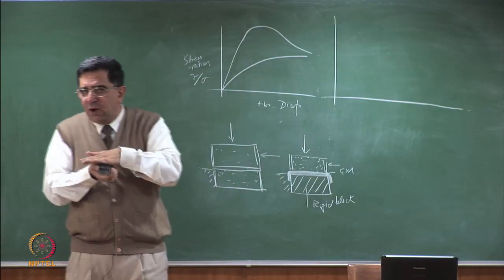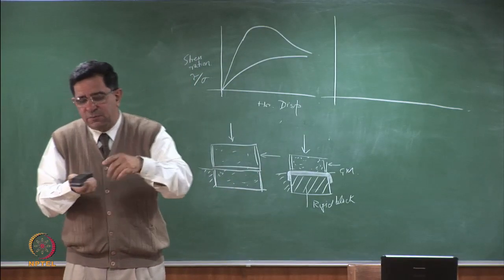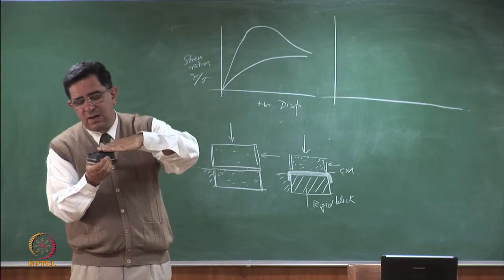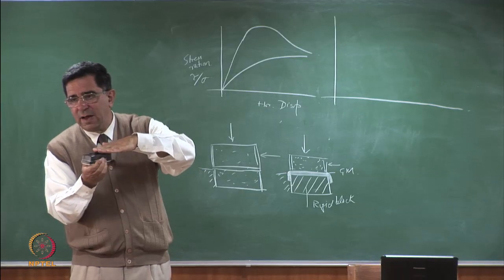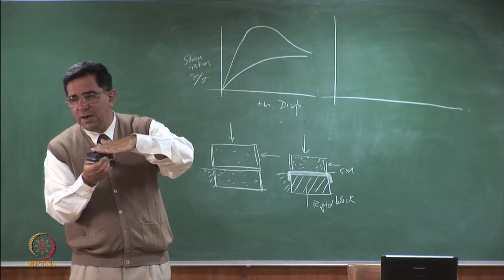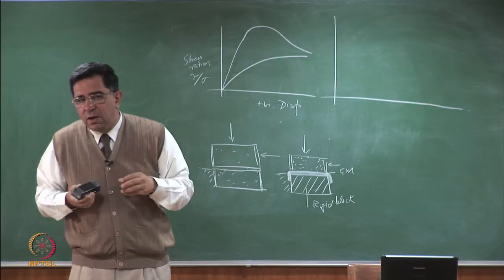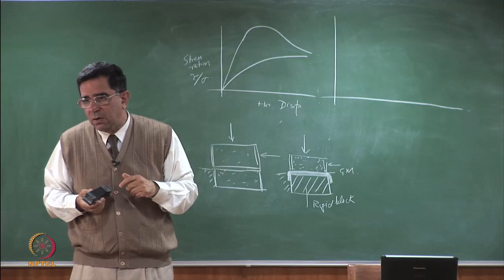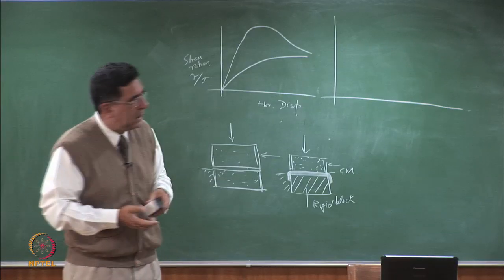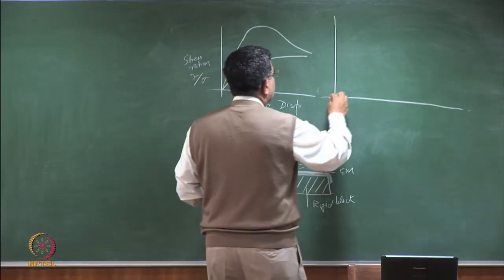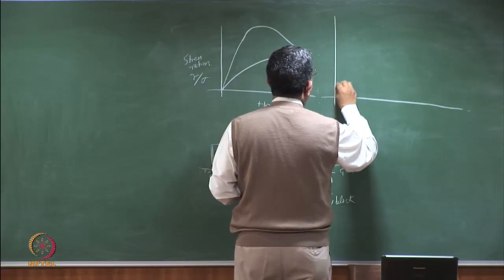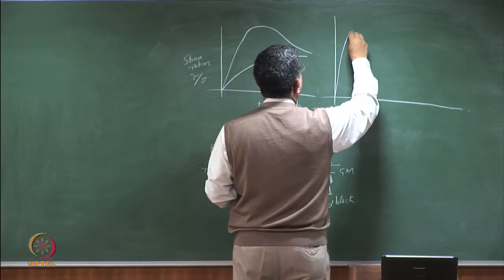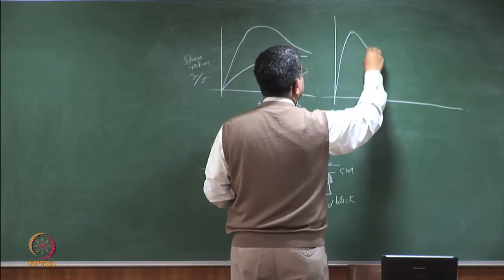An interface shear phenomenon is a slippage phenomenon. This is the bottom, this is a geomembrane, a smooth geomembrane. My soil is here. I move it, I'll get a friction angle or an adhesion. So will it require 10% strain to get a peak, or a 5% strain? No, the peak comes much earlier. Typically, the peak would come and then it would slip.